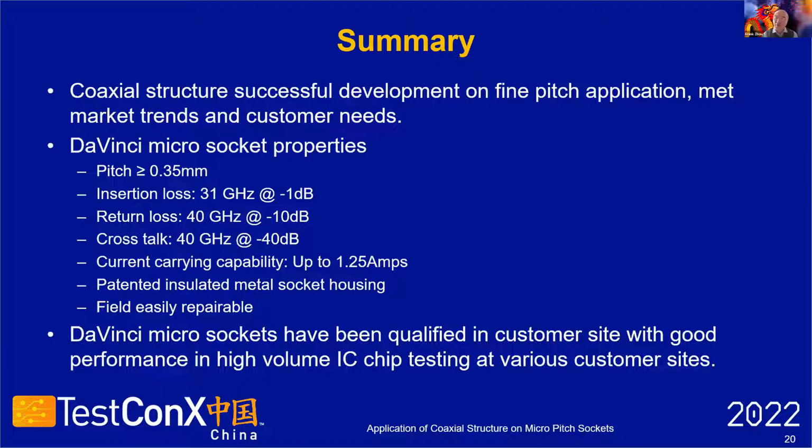One question from the audience: for the DaVinci Micro socket, the socket material is conductive, but you have insulation at the pinhole wall, and then the pin can contact the socket body. Is that correct? Yes, different pins have different functions, and they have different technical requirements for the surface. This is actually the know-how for the socket.